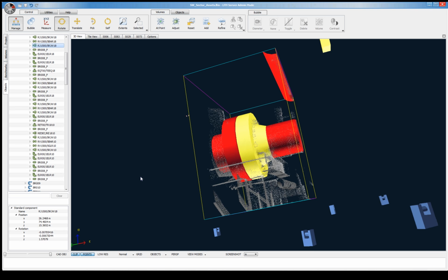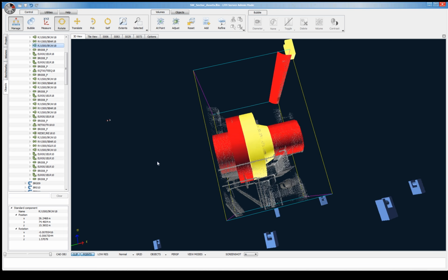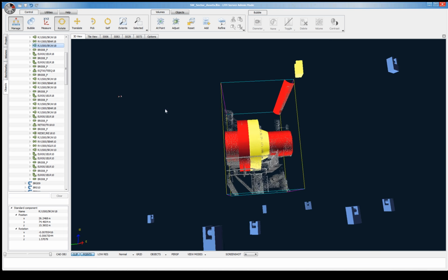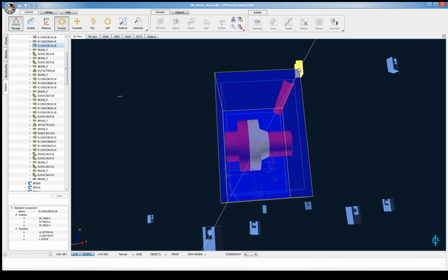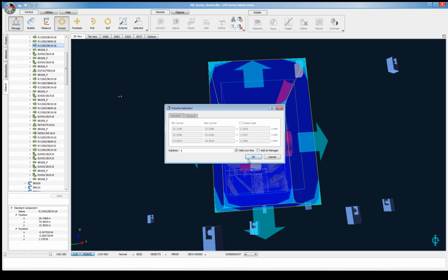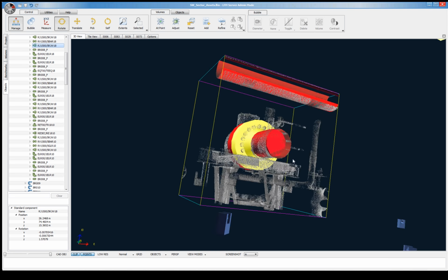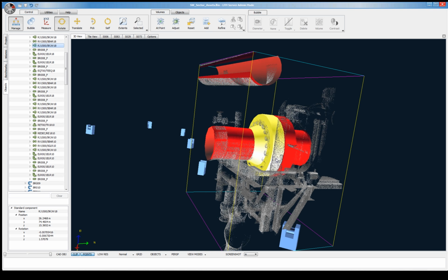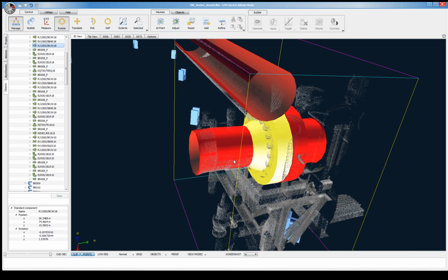Because we're looking at a particular flange here, I've called the volume around it. It's in amongst quite a congested area. So if you look at the bottom of the display, there's an option to clip. And clipping will just take everything away from the model that is on the outside of the box of interest. And that really, again, allows the designer to get a good feel for any potential problems.